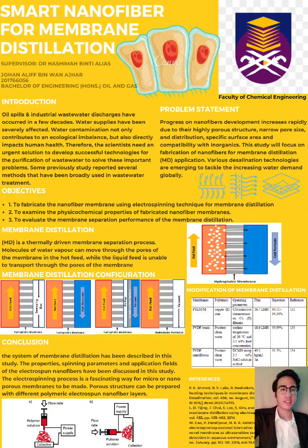All configurations have their own benefits and weaknesses. AGMD is known as having the best energy performance and efficiency. For commercial application, it is more common. The width of the air gap is normally in the 2 to 10 mm range, which is much greater than the thickness of the membrane, which is typically less than 300 nanometer.